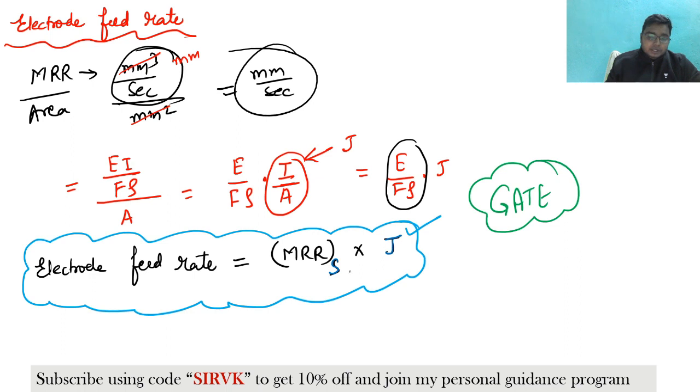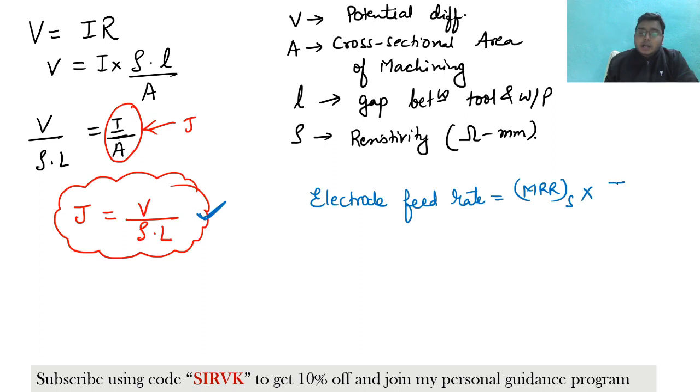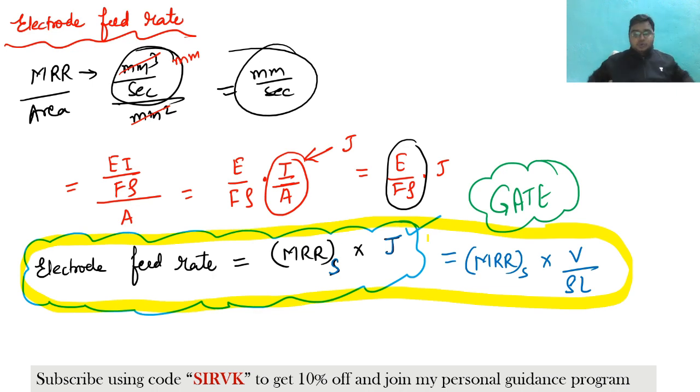Now see here, you can put it in the electrode feed rate equation. Electrode feed rate is equal to specific MRR into the current density. Now this current density is replaced by V by rho L, isn't it? So just remember this also, that this is nothing but specific MRR into V by rho L, clear? So this is a very much important formula. Electrode feed rate is given by this. Fine. So I hope these things are clear to you.